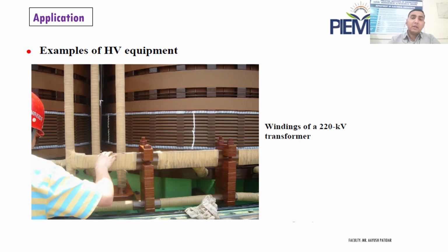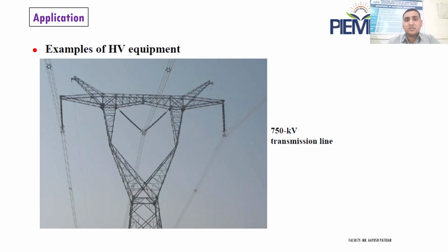Tests such as the delta test or megger test are performed on this insulation to make sure that when high voltage is applied every day, the insulation does not fail. If the insulation fails, there is an internal short circuit in the transformer, and it will cause an abrupt electrical failure of the whole supply. So high voltage equipment testing should be considered.